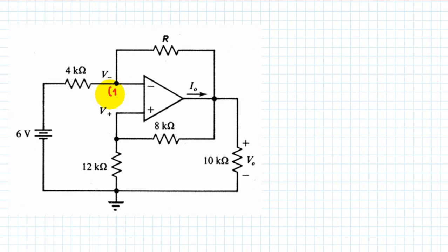Now we solve the circuit. Identify every node. The reference node has been chosen for us. Choose the direction for the currents in every branch. 0 amps for the input of the op-amp. It's an ideal op-amp after all, and then we write the equations.